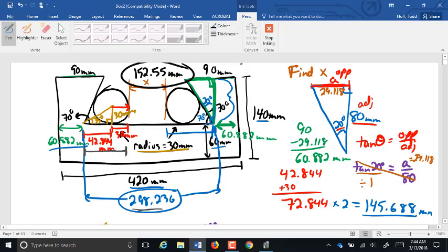Usually with millimeters, we only go to the 100th of a millimeter. Notice though that during my calculations, all of my previous calculations are rounded to the 1,000th. When I calculate, I always want to keep at least one digit past where I want to round my final answer to. Does that make sense? Because if I'm rounding to that hundredths place all along, my round off errors build up. If I'm rounding one digit past that, down to the thousandths place, there's a good chance I can keep those round off errors from building up and affecting my final answer.